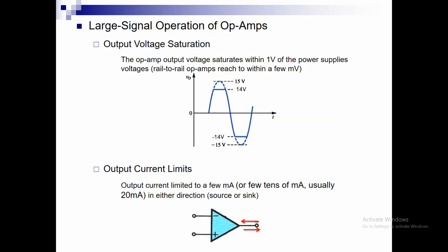The current may be decided by the heating, the maximum power dissipation that we can tolerate in the circuit. So you will have three constraints. One is the V plus and V minus, and a separate current constraint called I max.